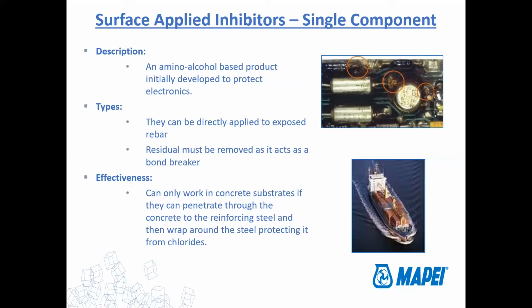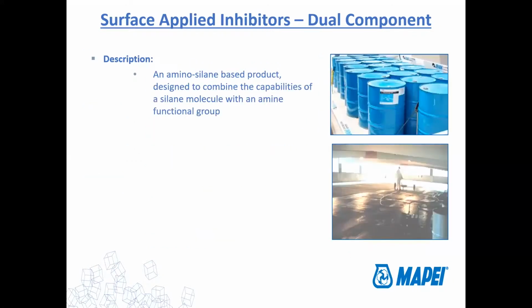from corroding. Well, we took that technology and moved it into the world of concrete and created these surface applied admixtures where, instead of just spraying it, you pour it on the concrete, it penetrates down and gets to the steel. The question becomes, does it actually reach the reinforcing steel? There's really no good way to easily test for that in the field. So there's a lot of hesitancy amongst people, and that's fair. I mean, I can't argue with them.